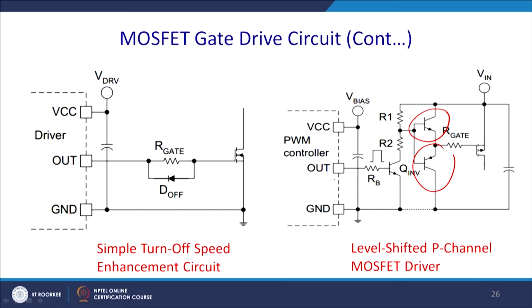Once you get a pulse, this NPN transistor becomes on. Once it is on, then this voltage becomes 0, automatically this voltage goes low. This will be in conduction mode; ultimately a negative pulse or a 0 pulse will be applied to it, and it will come to conduction mode. So, we have different kinds of configurations depending on different kinds of requirements.